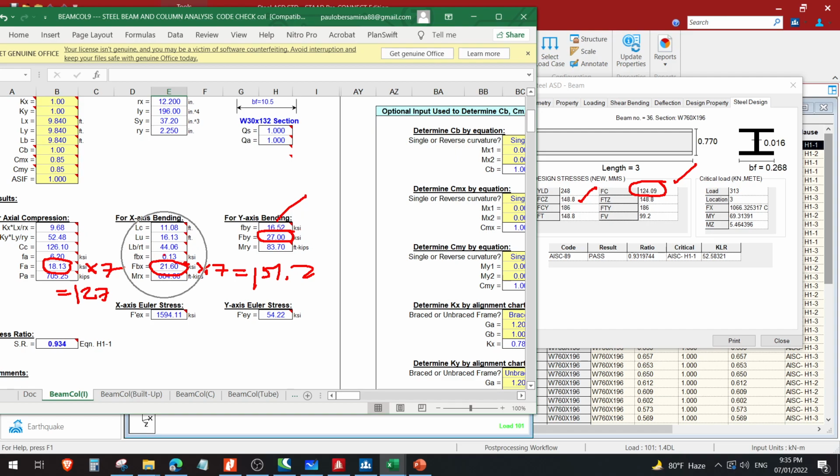Dito sa strong axis, yung kanyang actual bending stress is just 0.13. No? Napakaliit, no? Compared sa weak axis bending, 16 KSI. Talagang nadikitan niya yung weak axis bending capacity, which is 27 KSI. And if we check that, 27 times 7, that is 189 KSI, which is this one. Pretty close sa 186. And that's it.